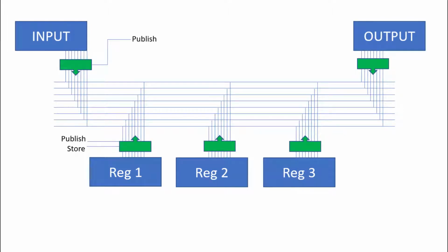Well, the way that is enforced is by gating the way that things are connected to the bus via some sort of switchable buffer. That buffer, which has to go between each thing on the bus and the bus itself, is switchable. So when the buffer is switched off, it's as if the register is completely disconnected from the bus. If register 1's buffer is off, it's like register 1 isn't connected to the bus at all.